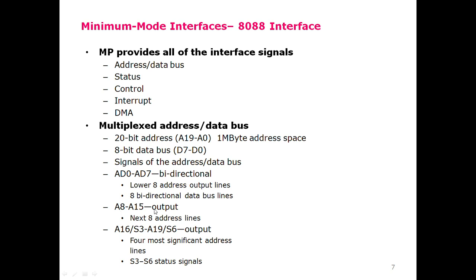A8 till A15 in 8088 are not multiplexed. They are output pins only, while these pins are bidirectional.